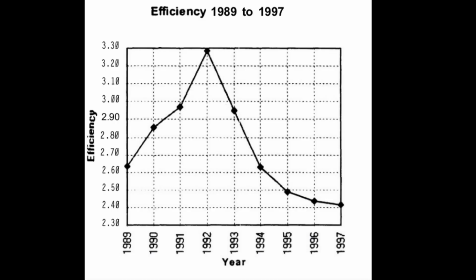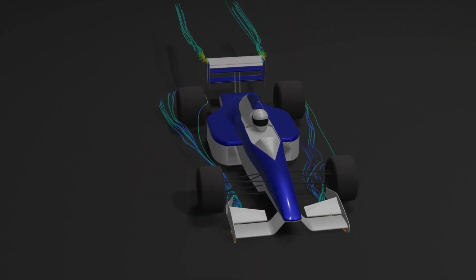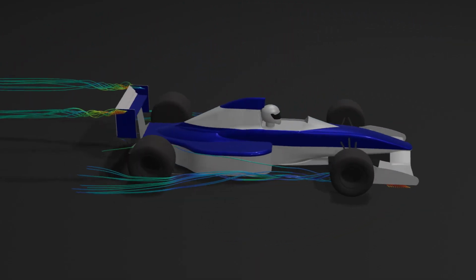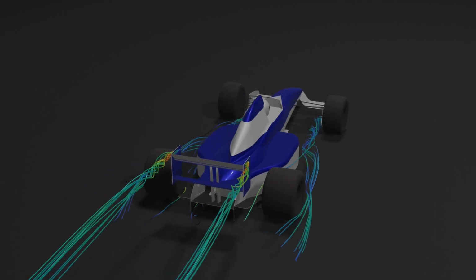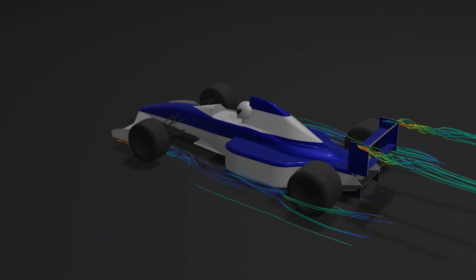The Gascoyne paper mentions the efficiency, so we might as well derive and compare the drag results. The efficiency was stated to be 2.86, where I got 3.19. It seems like this is mostly the wheels, as the paper states that there should be about 40% of the drag. I'm getting about 20%.